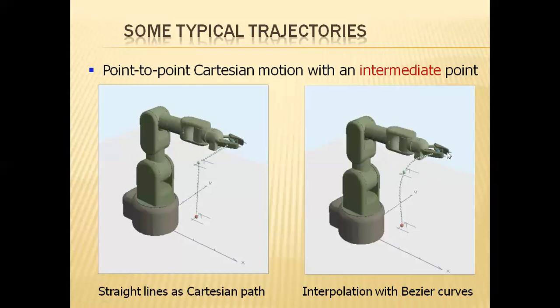This is the end effector which holds, let us say, a marker, and the marker will trace a particular path, that is circular interpolation. So the circular interpolation relates to the rotary joints or the revolute joints. And here the same traverse, which has the allowable movements of 6 degrees of freedom, will traverse in the form of a straight line. Hence this is called the Cartesian path in the first pictorial representation. And the second one is called the Bezier curves that are generated by the robots.